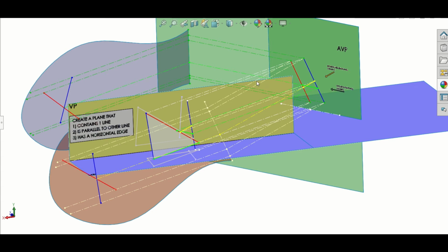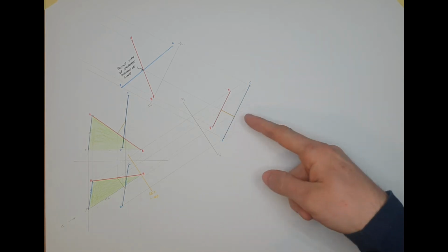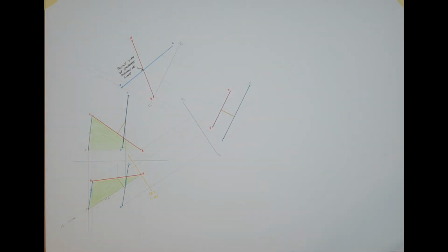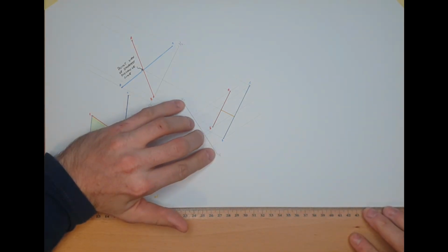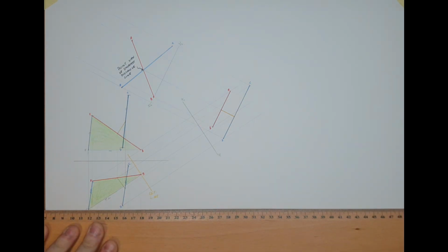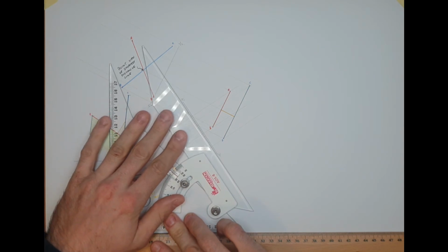Let's get back to our worksheet and let's draw this. So for this same set of lines, we're going to add in our next solution to a problem. And this time we're going shortest horizontal distance. So we've done shortest perpendicular distance by looking perpendicular to the lines. For shortest horizontal distance, we look at the two lines parallel, with the viewing direction parallel to the x1, y1, or to the ground.